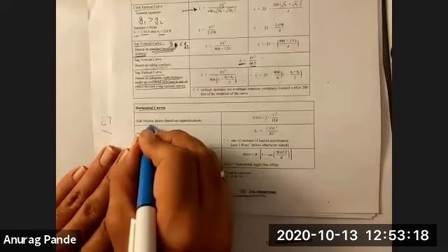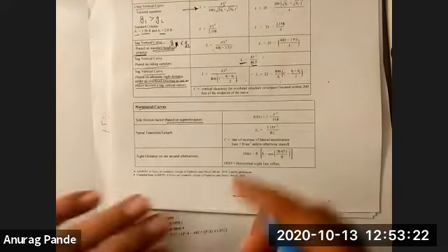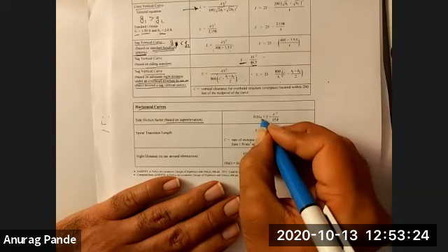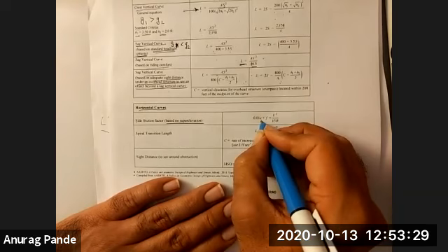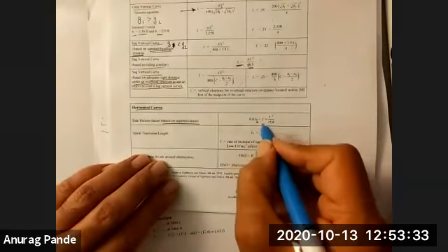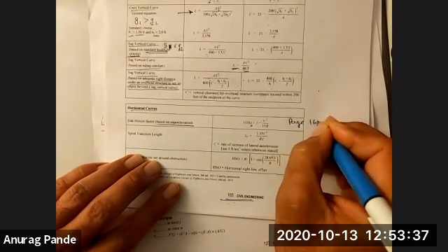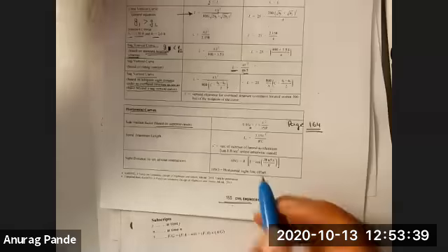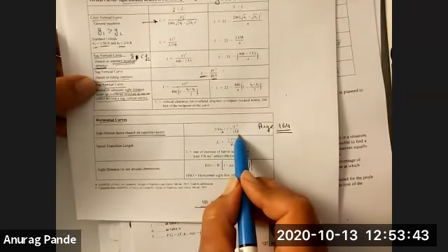So side friction factor based on super elevation can be used, and this will typically be given to you in the problem. Using this formula, you can figure out how much e you need. e is the super elevation. And all these values are from page 164. So if you go back to page 164, we can figure out small e, small f, and capital R.